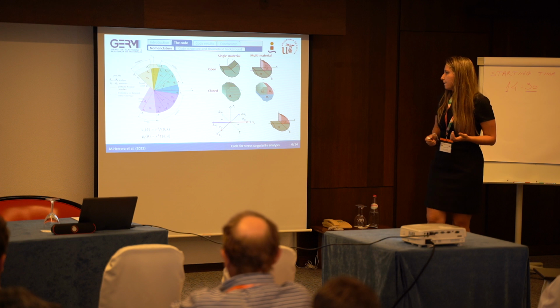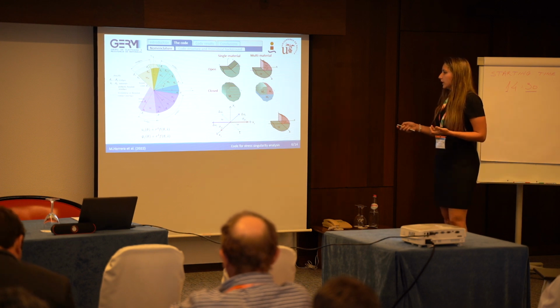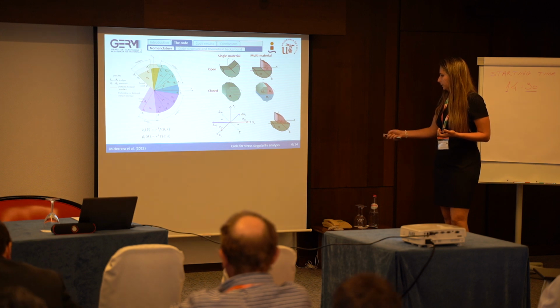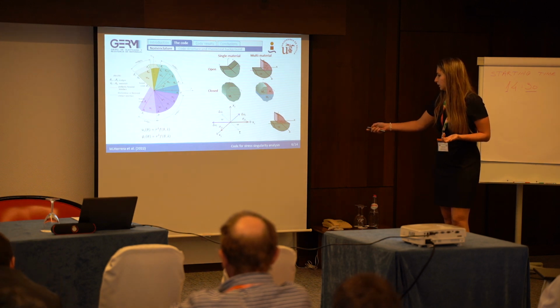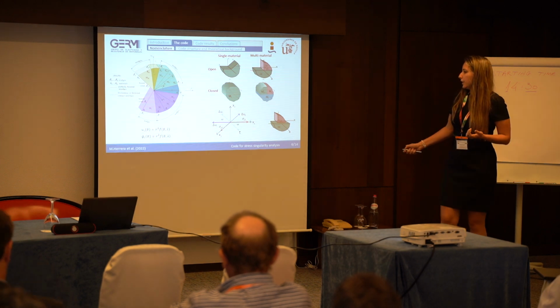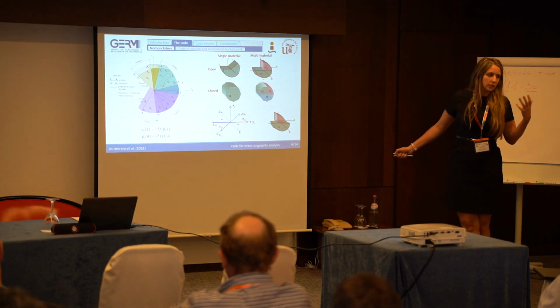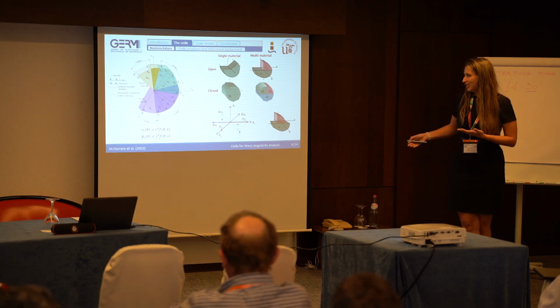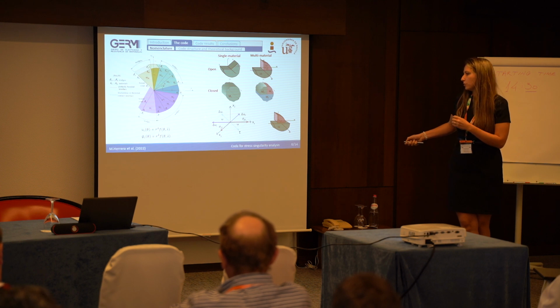When there is a frictional contact, for example in this corner, where you can see there is contact between both materials but they can move, we also define another parameter, omega. Omega is the sliding direction, or the shear direction, of one material opposed to the other.